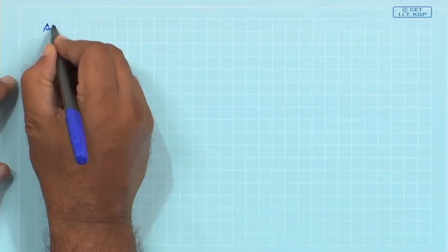Therefore, the next step of the problem is to evaluate the Reynolds number at x equals 1 meter, which is case 1, and at x equals 100 meters, which is case 2, and see whether they are in the laminar zone or in the turbulent zone. So, the next step is to evaluate the Reynolds number, which we are going to do next. So, at x equals 1 meter,